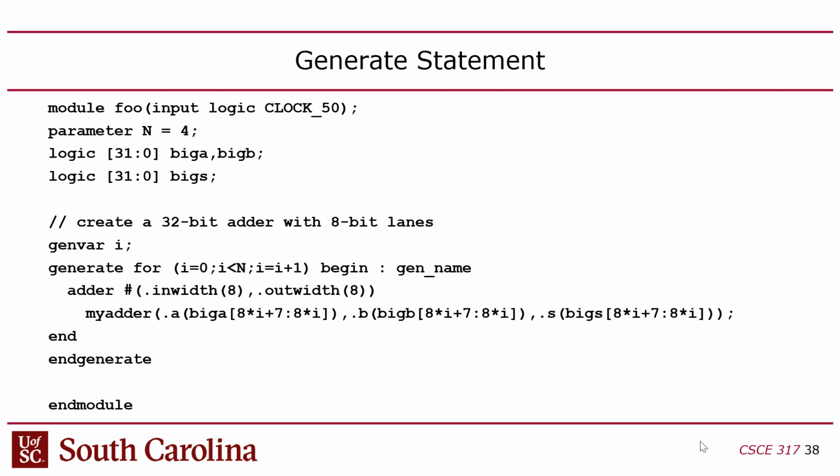You know, Sai? Well, we've got 26 LEDs on the board, right? So if we wanted to generate logic in order to control those 26 LEDs independently, we would use a generate statement to generate a pulse width modulator for all 26 LEDs, right? As opposed to just copying and pasting, which you can also do. You can copy and paste the code too, but it's a lot more convenient to use this generate statement, right?